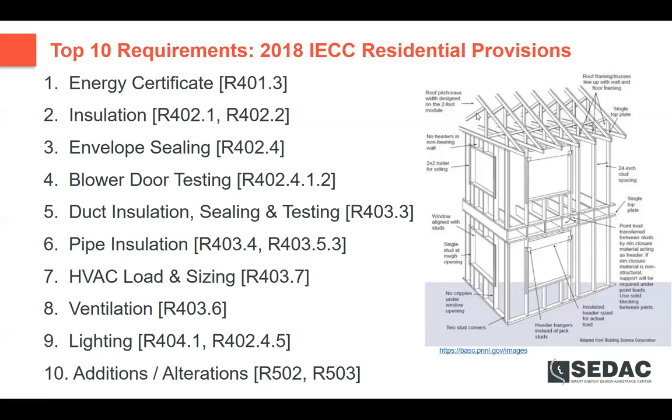Someone did notice that blower door testing is only in the residential provisions. Commercial buildings do not require it, but they do have an option for pressure testing. The GSA has done some studies, and I believe the Army Corps of Engineers requires blower door testing even on all of their commercial buildings, not just their residential buildings, because they've found deficiencies there.